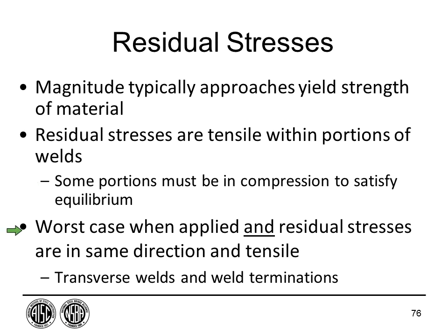The worst thing, though, is when our applied stresses, so mechanical stresses, dead load, live load, and residual stresses are both in the same direction and in tensile. And of course, then they add up in a way. Now, we don't specifically add them up, but we worry about their effects in fatigue.